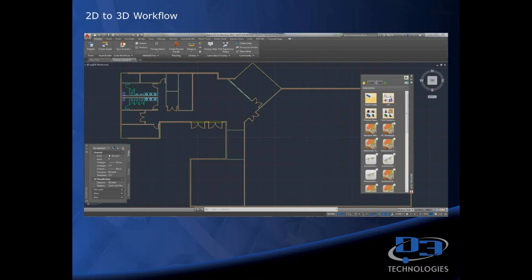Another type of asset that we have are cloud-based assets. If I come in here, you're going to see this factory icon with the circle on it, which indicates it's a cloud asset. To have access to that, I simply need to right-click on the asset, and then I can select download. Now I'm going to show this in real time. Just in a matter of moments, it's grabbing this from the cloud, and now it's ready to be used within my factory layout. It's really nice to have access to those cloud-based assets. And then again, I mentioned we have user assets, and these are custom assets that you've published or your company's published, either that you've created in Inventor or got from a vendor or something like that, and have been published and defined as an asset.